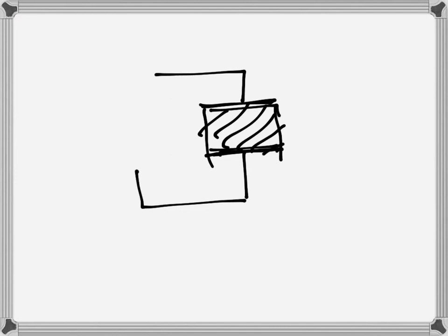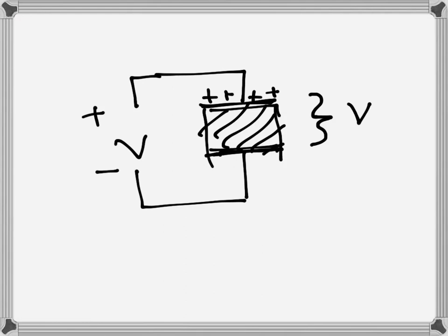Now when a DC voltage is applied across a capacitor, it actually blocks the DC. As a result, charge is stored across it, and when we say it blocks the DC, that means it is as if an open circuit. The applied voltage comes across this, so this voltage will also be V, but there is a process through which it happens, and during that process a transient current flows through the capacitor. So the transient current goes something like this.